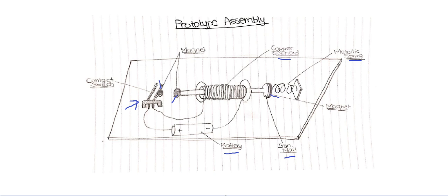As the end of the nail where the piece of magnet is placed approaches the piece of magnet on the contact switch, both magnets repel, allowing the spring to pull the nail in the opposite direction. It pulls the nail back, returning it to its initial position, and at the same time the repulsion causes the contact switch ends to come in contact, closing the circuit again and producing an instantaneous magnetic field that will start the motion over.